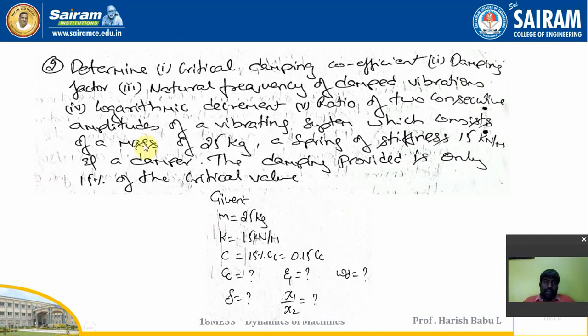So in this video, we're going to see the problems on damped systems. So let us consider a problem. Determine the critical damping coefficient, damping factor, the natural frequency of a damped vibration, the logarithmic decrement, and the ratio of two consecutive amplitudes of a vibrating system, which consists of a mass of 25 kg, a spring of stiffness 15 kilonewton, and a damper. The damping provided is only 15% of the critical damping. So this is the question they given.